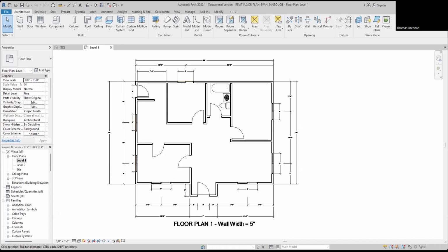So I've got that. Now what I'm going to do here, and I think you guys should be able to see this okay, I want to pay attention to this right here. This is a 40-foot dimension at the top. So the first thing I do is I take my scale and I rotate it till I see 20. All right, 20 is located right there. You can see it right there, 20. And then you take this and you place it here, and then you take a look at it and you go over here.